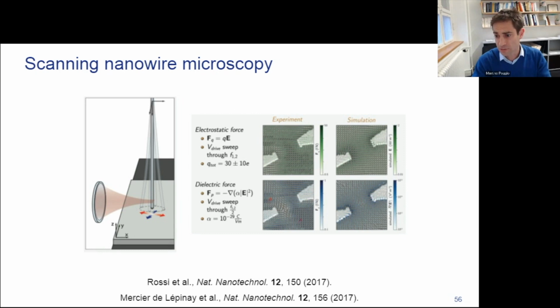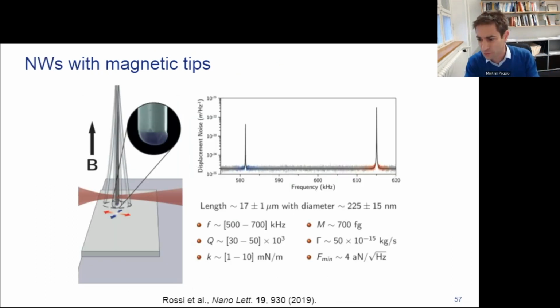What's very nice about this is not only that you have this directional information, but that you're measuring really tiny forces, much tinier than are normally measured by atomic force microscopes or magnetic force microscopes. In order to bring this back to what I was originally talking about, magnetic imaging, we need to functionalize these nanowire force sensors with a magnetic tip in order to make a kind of nanowire MFM. This should give us a very, very sensitive version of MFM. So with some collaborators at the University of Regensburg, we did some work trying to put magnetic tips on the end of gallium arsenide nanowires. What you see here is a manganese arsenide ball, a little magnetic tip grown in an MBE on the end of a gallium arsenide nanowire, and this provides a really nice point-like MFM.